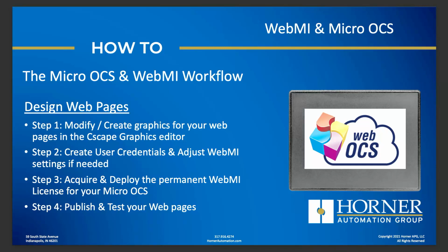And then when you're done with that, now you need to acquire and deploy a license for this controller to run WebMI. Now, WebMI is not an included free feature, although it does have a limited function version available for free that's just, I think, 5 data objects in 1 screen. But in general, the way most people use it, it's a one-time upgrade that is licensed, and there's no ongoing cost. It's just you acquire that license from Horner or from your local distributor, you deploy that license on the unit, and then forevermore, that unit has WebMI capability.